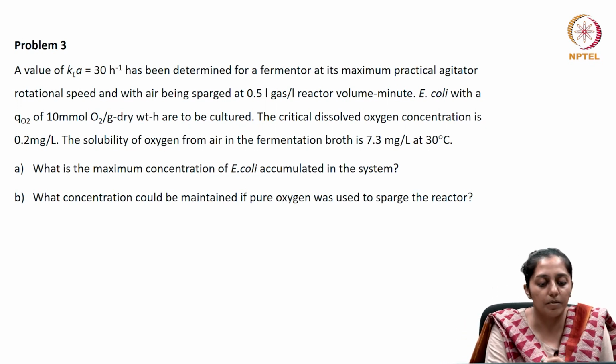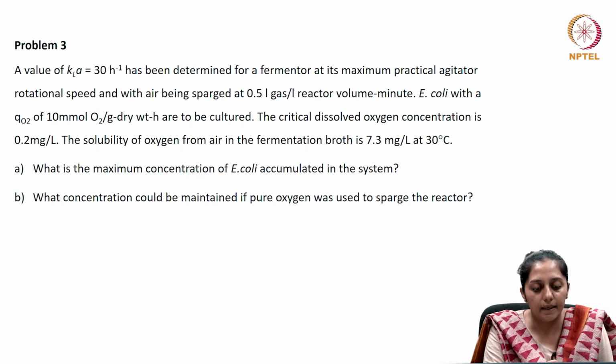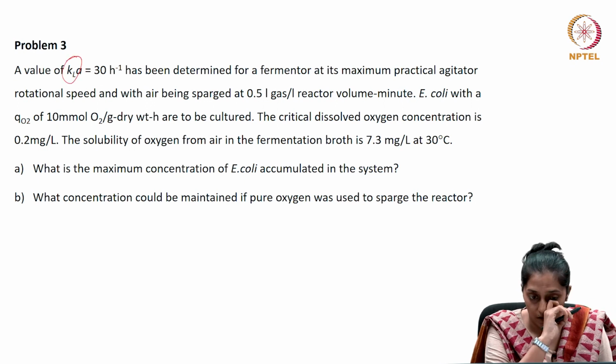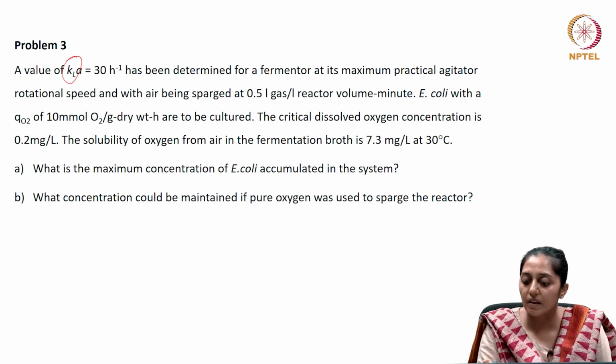Let's see the third problem now. A value of KLa is given as 30 hour inverse. So, the volumetric mass transfer coefficient of the system is known for a fermenter, at its maximum practical agitator rotational speed, with air being sparged at 0.5 VVM.